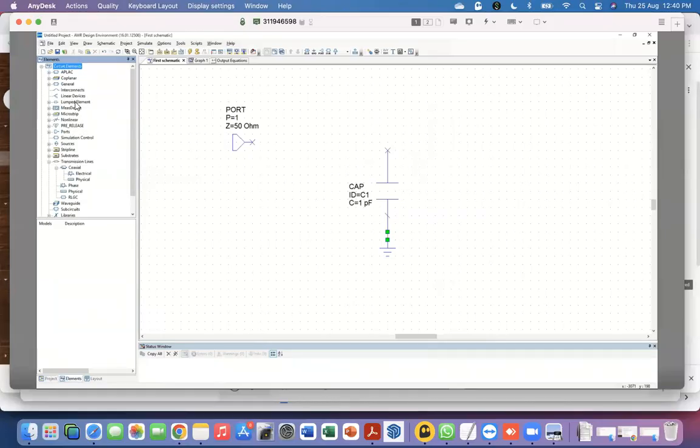The most common ones we use are these so-called lumped elements. Okay, so maybe this is a good chance for me to say something about lumped elements as well, because this is one aspect of circuits which we are familiar with, and this is actually the main point which distinguishes conventional electronics versus microwave frequency electronics. And that is the absence in the microwave domain of ideal lumped element circuits or devices.